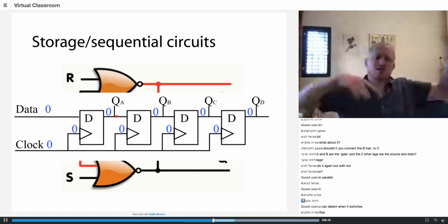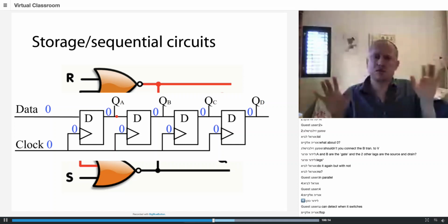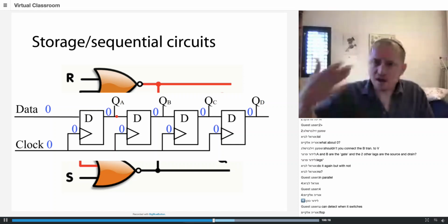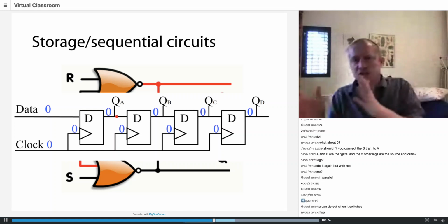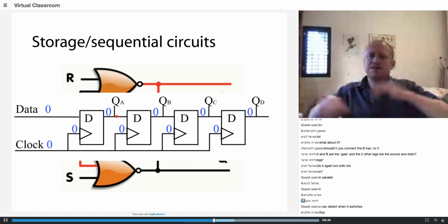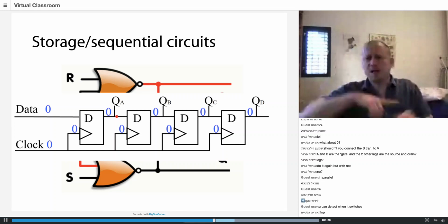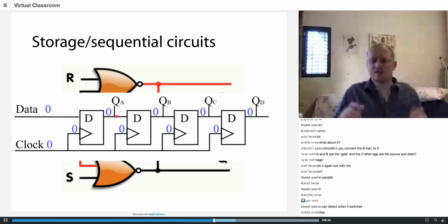You can have all sorts of logic elements which do all sorts of computations. But you wait enough time between the clocks so that all the computations are finished. So you bang the drum, there's a big shift because all the D goes to the Q, and then they run around and do all the logic, and then you bang the drum again, and this is how you do synchronous logic. It's very useful.